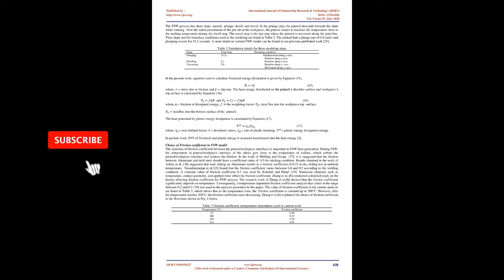Secondly, to perform a parametric study by varying the important weld process parameter, rotational speed, and analyze the response from different models for the purpose of understanding the energy generation of FSW. The Pintool rotational speed was chosen to be varied from 200 rpm to 450 rpm based on earlier experimental investigations by our research group [32].